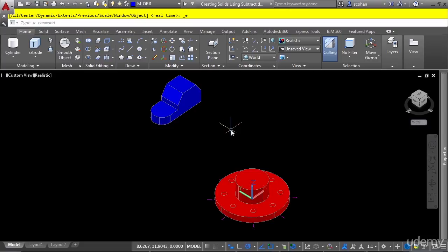Upon completion of the command, the first set of selected solids are unioned together, and then the second set of solids are subtracted from the first set. All the selected solid models are consumed into that new composite solid. The solids that were subtracted from the first set are no longer available for future Boolean operations.